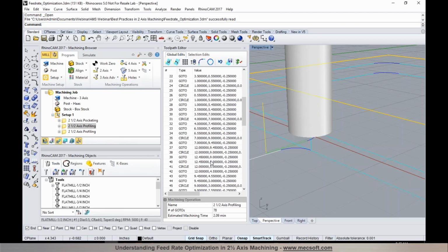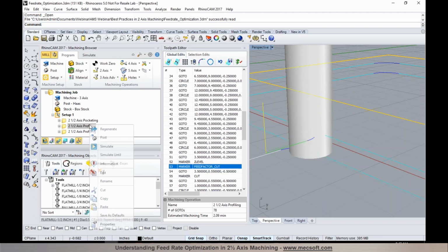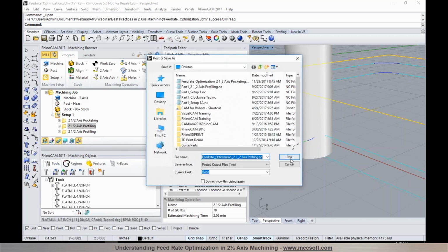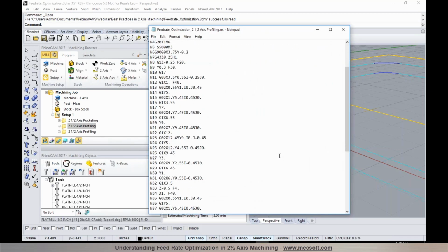And you'll notice, as you take a look at the toolpath viewer, that as it plunges between the levels, it reduces the feed rate. So when you post-process your toolpath as well, you will see that the feed rate is being reduced as you plunge between levels. You'll notice that the feed rate drops to 10% of your actual cut feed rate. So it drops to 10%, which is a feed rate of 4 inches per minute in this particular example.